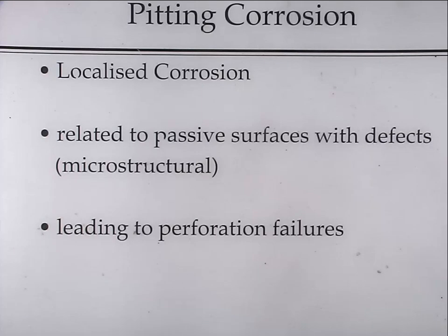And the same is true of the example on the handout where the coating has been damaged and all the current is focused in one area. So it could be a coating, it could be a passive oxide layer. So in steels you get Fe3O4, you get magnetite at higher temperatures, then that's a passive coating, and you can get pitting in magnetite coated steels.